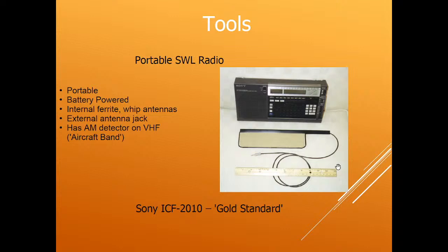And we'll see later that this had the advantage that you can use a small Yagi like this one here to actually locate and get some direction bearings on an arc or some kind of an RFI signal. So if you hear a signal on your radio, say on 20 meters, if you can correlate it with a signal that you can hear on this radio on 135 megahertz, then you're in luck. You can use the little antenna to triangulate on it and track it down.